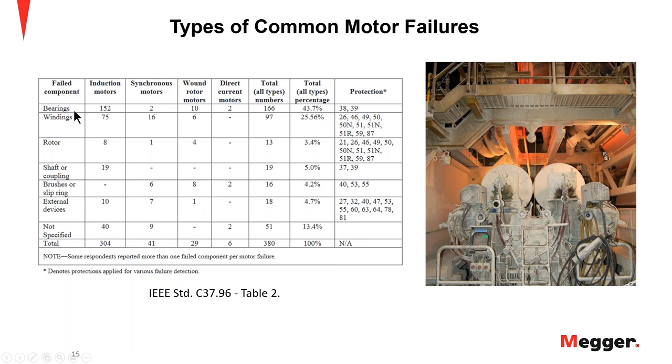So when you look at the chart here, just as they have labeled in this IEEE standard, you have the bearings. You have induction motors and synchronous, the two that are more prevalent in the industry. Of course, the induction motor, and then it gives you the modes of failure. As you can see, the bearing failure, which most of them have, with all the moving parts and so forth, is at the top of the table here.